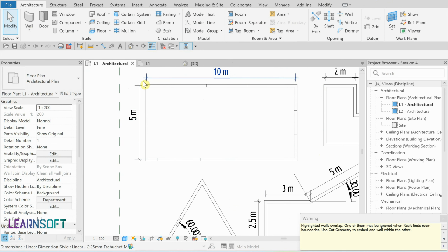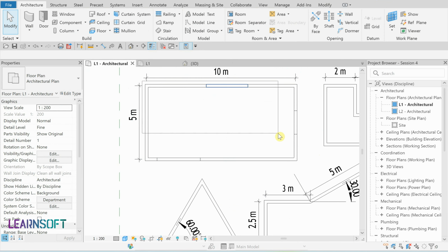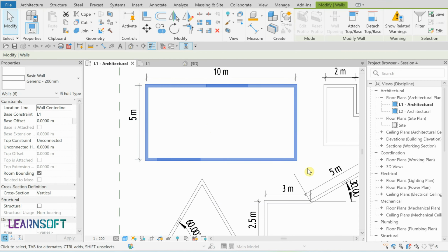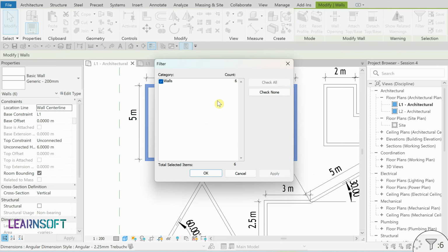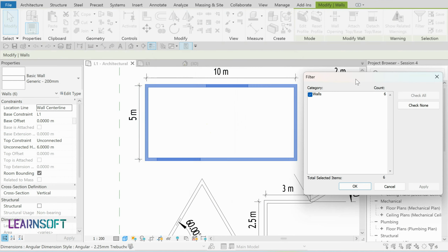Window selection is a good option to find overlapping elements, select and modify them. Select the Undo function to learn an interesting point. When there are several overlapping elements, to find them efficiently, I suggest window selection. Select all, then use a filter to refine elements. Let's see how it works.